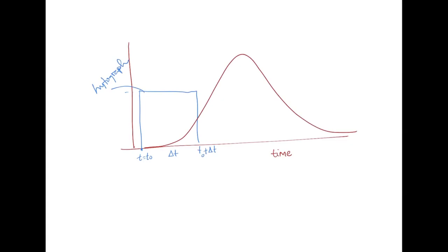Usually the times will be given here. Let's say this is 1 minute, this is 10 minutes, this is 25 minutes. Not to scale, but I'm just saying. If I ask you what the lag time is, you'll know that the lag time is the difference between the peak and the center of the rainfall.